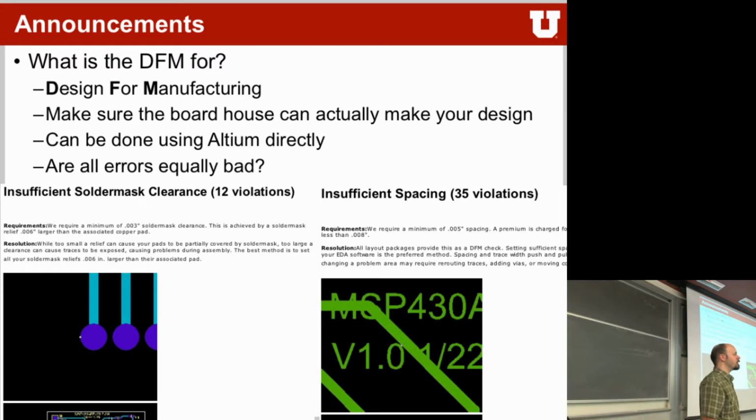Did you reduce that, or did you set it to 0 mil expansion to avoid solder mask slivers? Probably. What can happen is if you actually make an expansion, it expands so much that there is no solder mask in between these two pads anymore. And then it becomes more difficult to solder, because you can bridge these two pads. If you look at the PCB, if these two coppers are so close together and there is no filling in between, it's very easy for solder to go in here and bridge these two. But if there is solder mask in between, bridging is avoided more often than not.